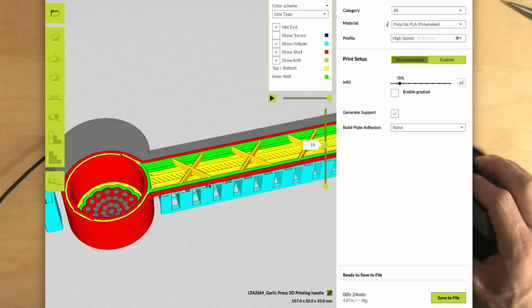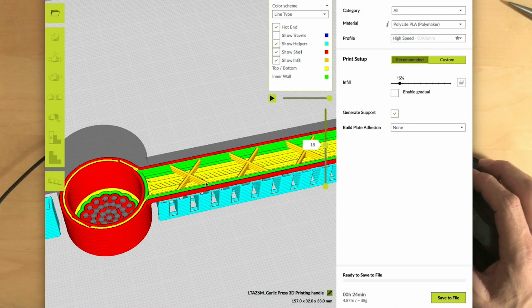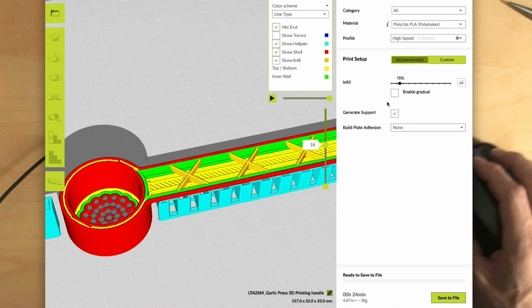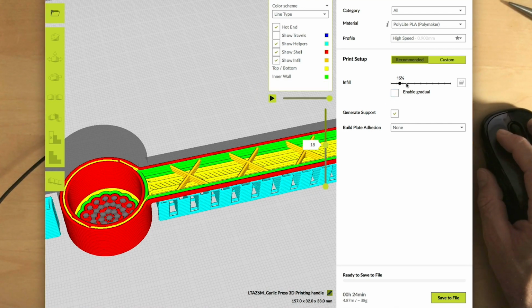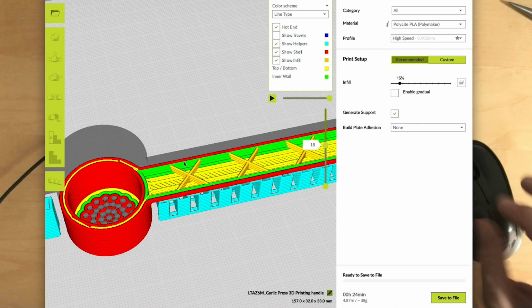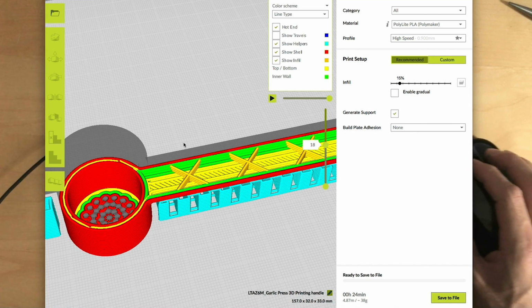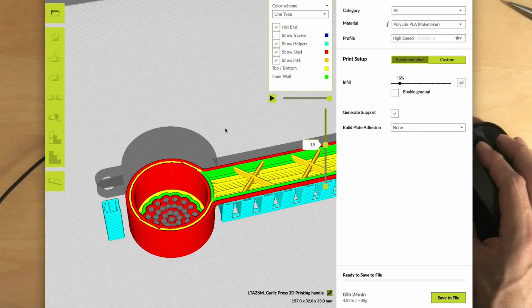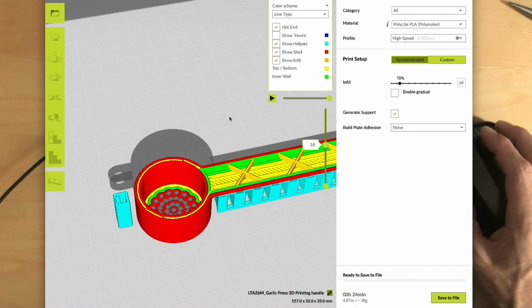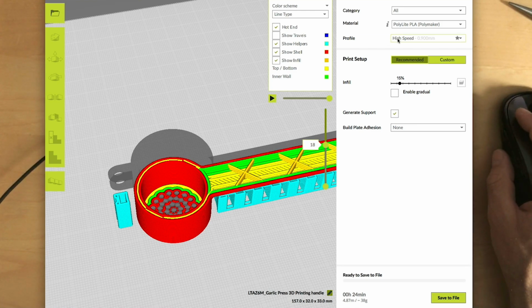Now another thing, because the handle is kind of solid, you don't have to print it solid. That's the reason why we have this infill that basically takes a solid object and then cores it out. And another thing that is important to keep in mind here is while the nozzle has a height for the print, it also has a width.